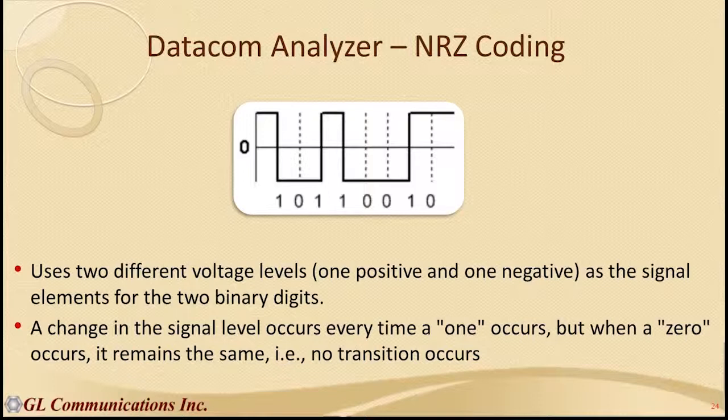In other words, just have one circuit, transmit data and receive data, and the clocking is embedded within that signal. So the transmitter adds clock and data in one signal and transmits it. That way you're saving on some wires. And the receive side extracts the clock and the data and separates them.